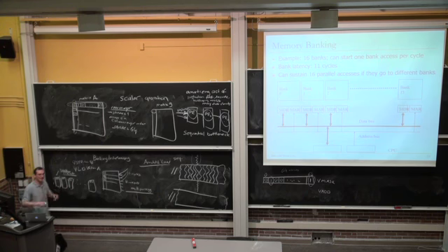So you're not really getting the parallelism you want. Even though all of the operations that you're going to do on those elements are independent, just because they're mapped to the same location in memory, and you need to access them one by one, and memory takes more than 1 cycle, your throughput is reduced. So that's why it's very important to provide enough memory bandwidth.